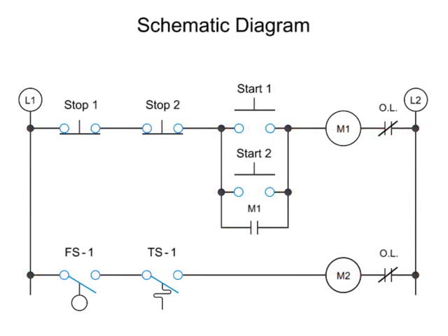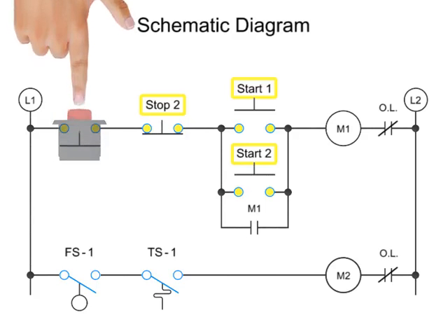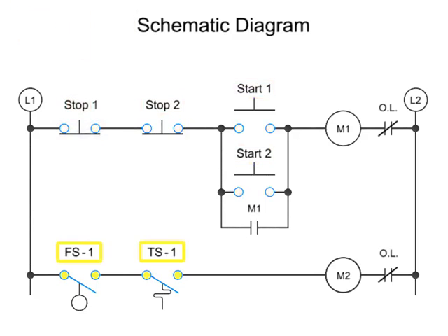In determining the operation of an electronic circuit, it's important to consider whether a switch functions manually or automatically. Manually controlled components require physical manipulation to work. Automated components turn on and off without manual intervention. A typical example is a float switch found in a sump pump. When a rising water reaches a certain level, a float switch is activated that turns on a pump to expel the water from a tank.